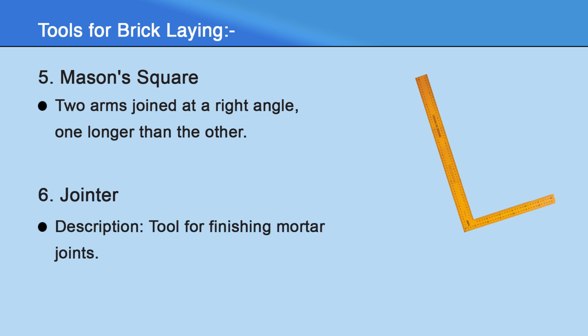Next come jointers. A jointer is a tool for finishing mortar joints, used for shaping and smoothing mortar, creating a neat and uniform appearance of joints, and making different joint profiles such as concave, V-shaped or raked joints.